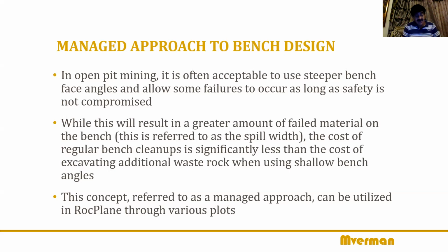In fact, they struggle to find space for the dump slopes, because the material that you extract, you have to dump somewhere. It's a problem. Even for dumps, they can take it vertically high, but not so widthwise. So they keep thinking about innovative ways of making those dumps stable. So if you cut it steeper, or cut it flatter, the whole thing changes.